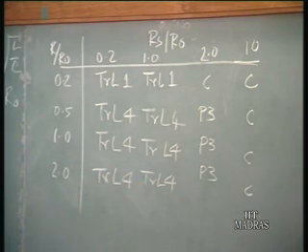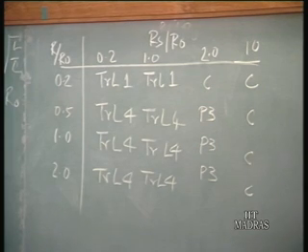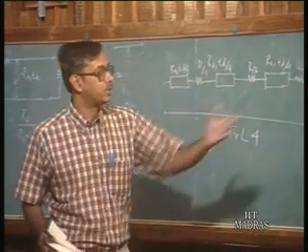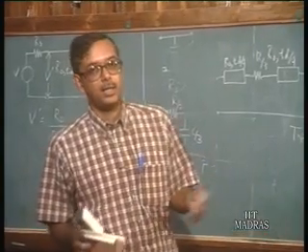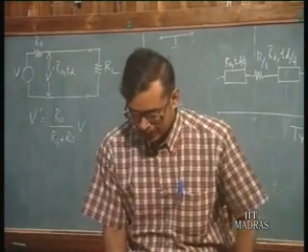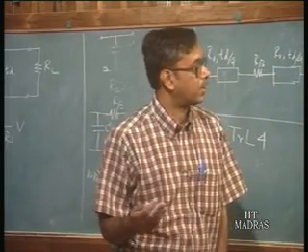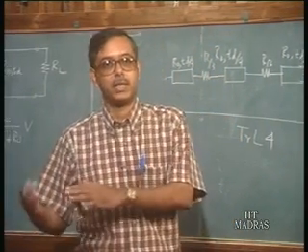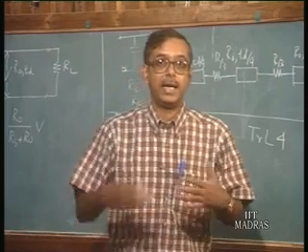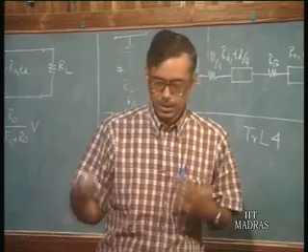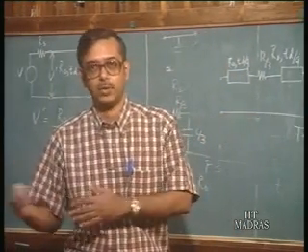So, when we do an analysis, we have to look at the particular situation and see which model will give us the best results in the shortest amount of simulation time. So, using this table we can do the simulation in the shortest possible time. For example, we can just take a capacitance model in some situation and get the same results as the transmission line model in a much smaller amount of time. So we should always go for that.